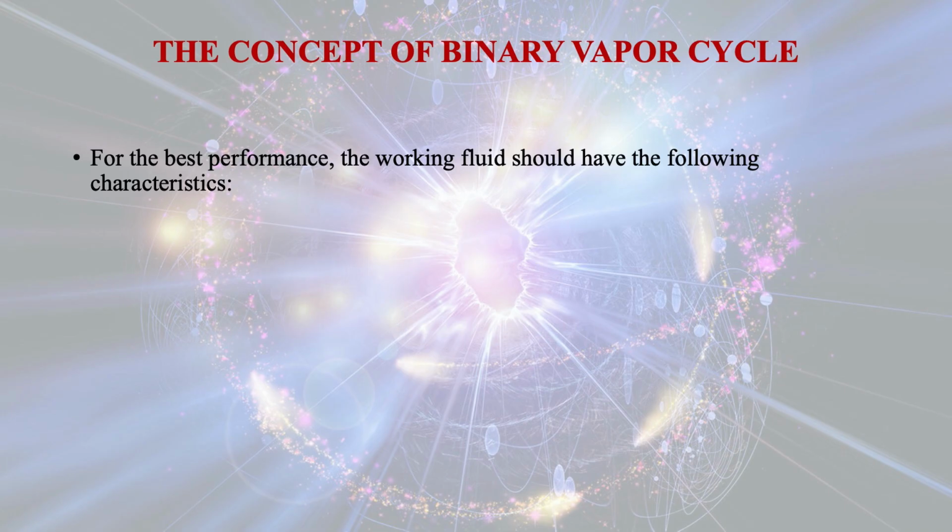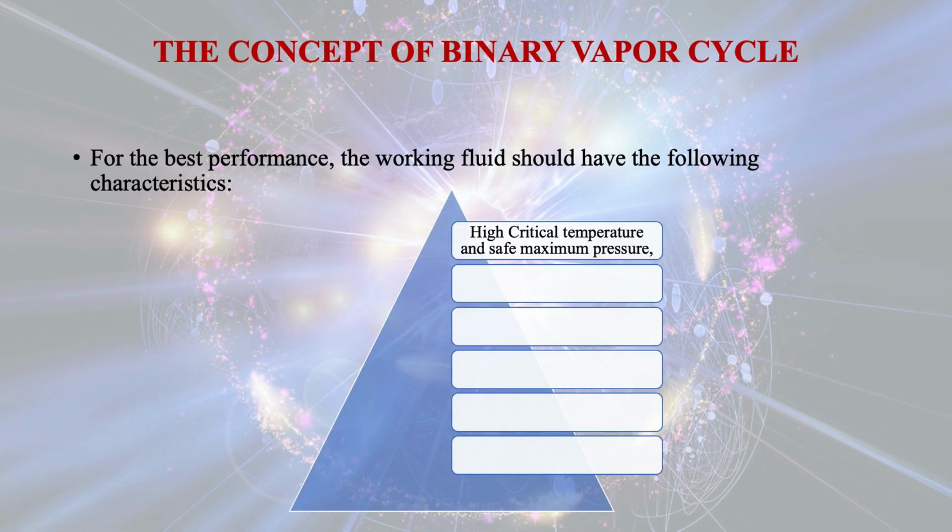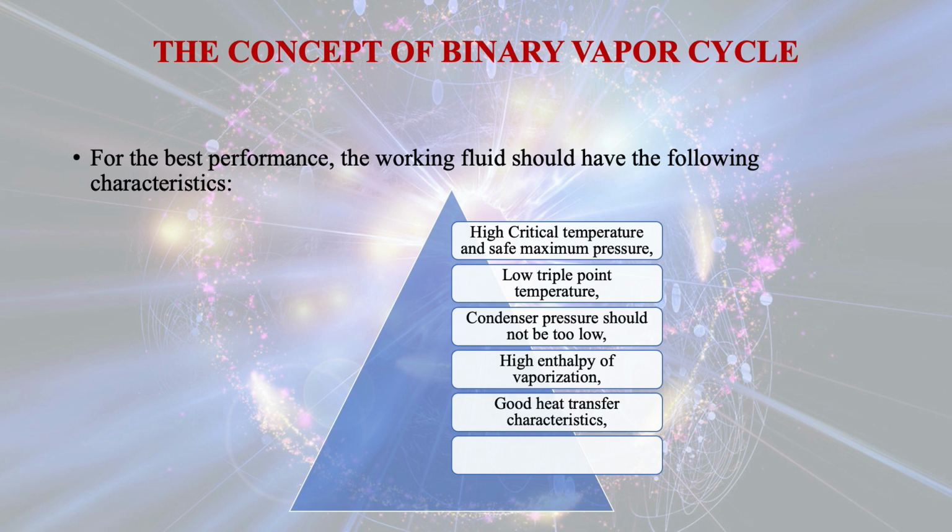For the best performance, the working fluid should have the following characteristics: high critical temperature and safe maximum pressure. Second characteristic is low triple point temperature. Next characteristic is that condenser pressure should not be too low. High enthalpy of vaporization, good heat transfer characteristics, and finally it should be easily available at low cost.